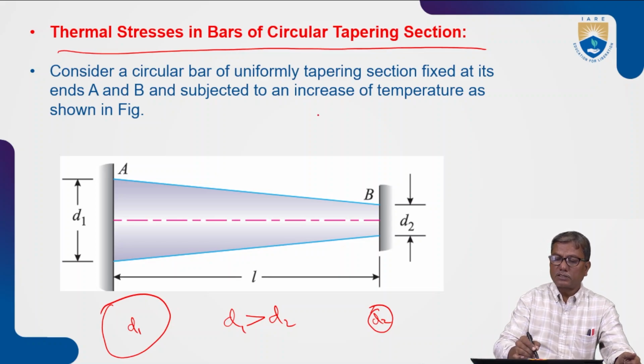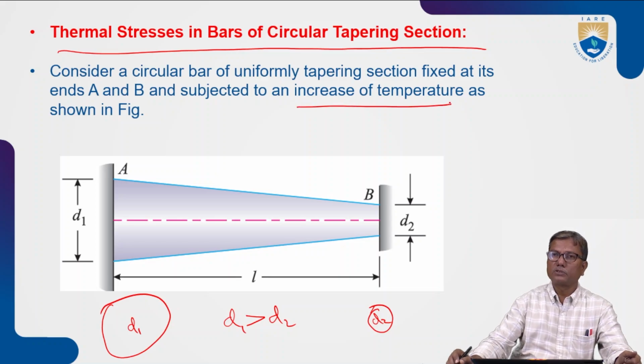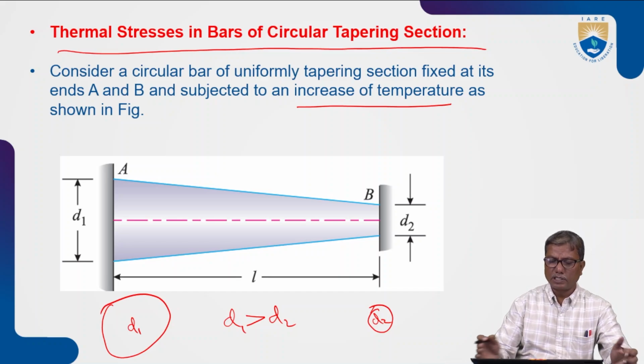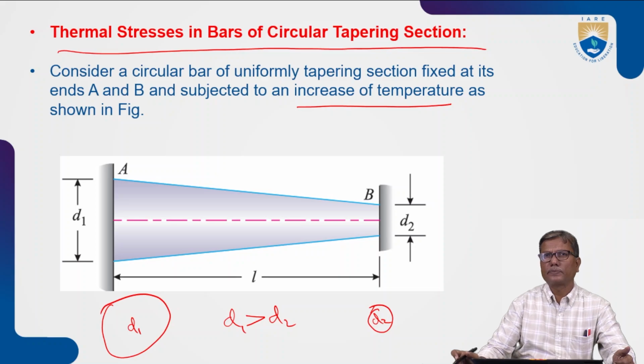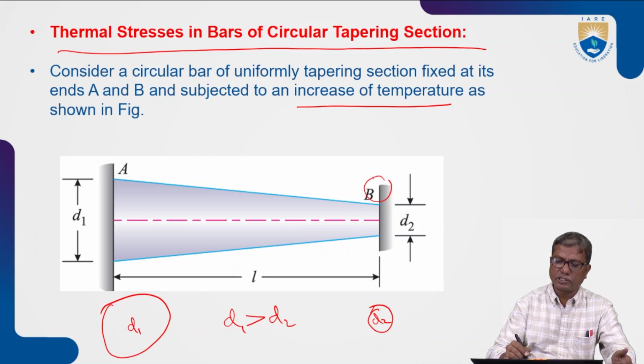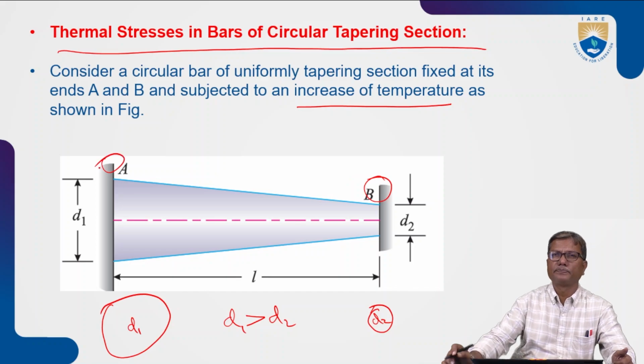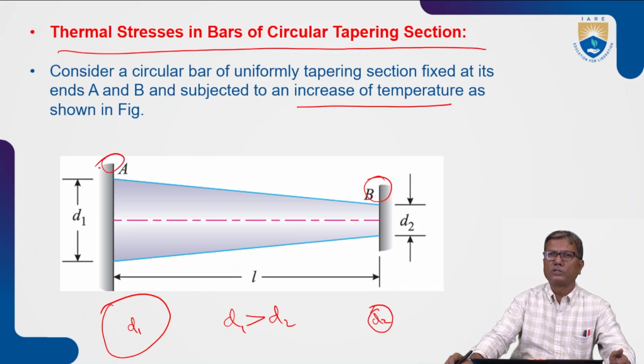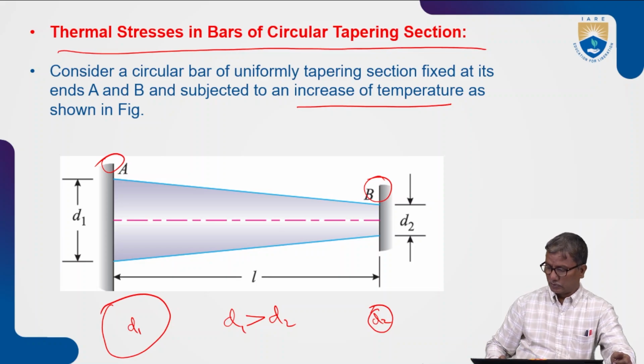It is subjected to an increase in temperature. So the tendency is to expand, which is prevented by the supports provided at ends. So it causes compressive stress.